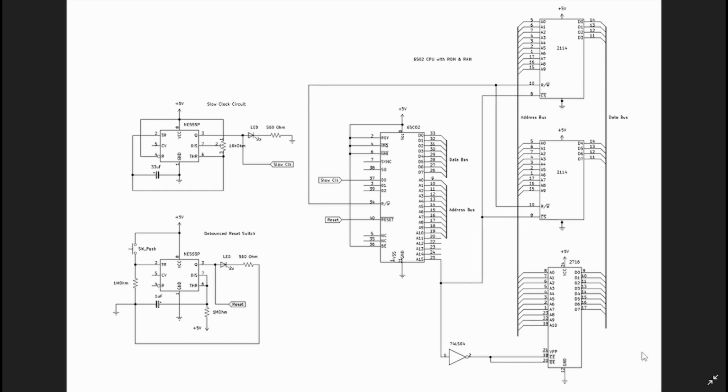Now you'll remember from the last episodes that the ROM was replicated because it's only 2K, hence the same thing with the RAM, it's only 2K. It is replicated all the way up to 32K, and then after that 32K it's all ROM. So it will be repeated. Now for the test that we're doing, we're only specifically targeting two areas of ROM and RAM, so it doesn't really matter. But we can modify that if we need to, if we want a more complicated circuit.